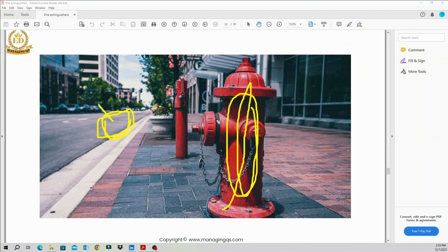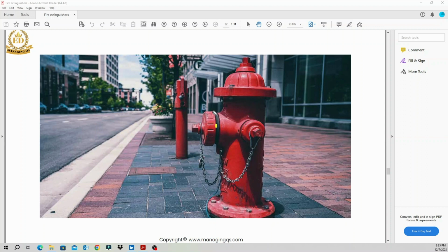So at that time we can use this fire hydrant. We just scroll this and remove it from this portion of the fire hydrant. Then the water comes out with high pressure. We just connect the fire hose to this point, then the water comes into your fire hose. So we should understand that the fire hydrant system is another one of the firefighting systems, right?